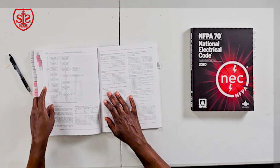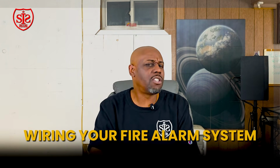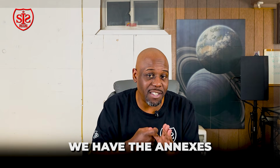And then also you have Annex B, which is your engineering guide for detection. This is what the engineer would be using when it comes to system design, evaluation, smoke detector placement, if-then scenarios. And then you also have the wiring annex, which is your Annex F. It gives you the wiring diagrams for Class A, Class B, all different types of classifications when it comes to wiring your fire alarm system. So just to recap real quick, we got Chapter 3, Chapter 10, Chapter 17, Chapter 21, and we have the annexes that we want to pay attention to when we're taking our NICET Level 1 exam.